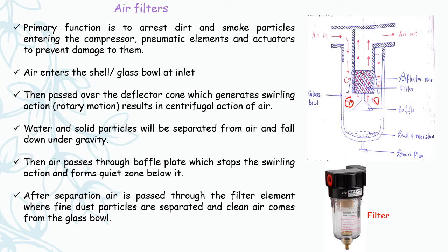So because of this, water and solid particles will be separated from air and fall under gravity. Then air passes through the baffle plate. This baffle plate prevents the swirling action and forms a quiet zone here. You can see near this it forms a quiet zone.